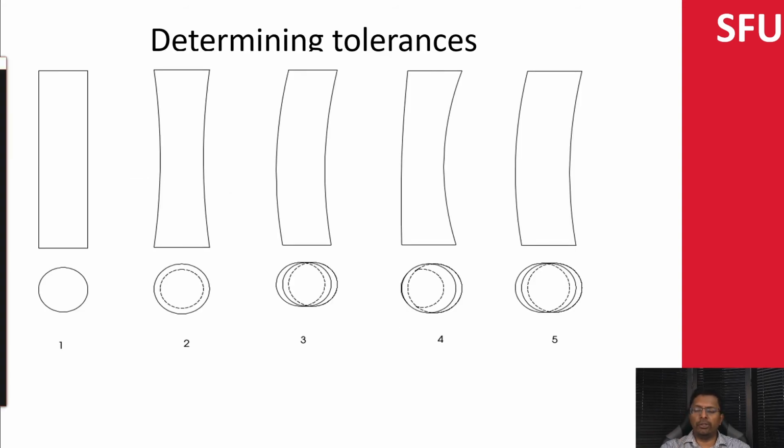So welcome back. I've just rearranged my drawing into one sheet so it's easier to follow. What I'm going to do is mark off multiple cross sections. I'm going to pick maybe 5 of these, then mark off the center axis over here. Then I'm going to mark off these values, so maybe 5, and then mark the centers over here, and then we can measure the dimensional and geometric tolerance over here.